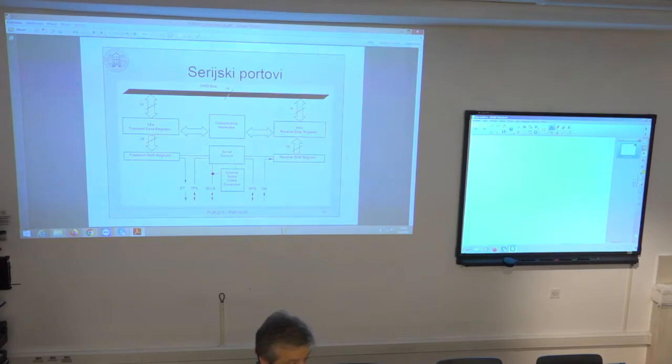And you would have this serial bus and corresponding controller typically on most of those DSPs. Because in this case, they will automatically take the values from some AD converter that takes the analog value, converts it to a digital value, and then serially transmits one bit after another to the DSP. And the DSP, in this peripheral controller, combines these bits into a word and interrupts the CPU only after the whole word is received in the input register.